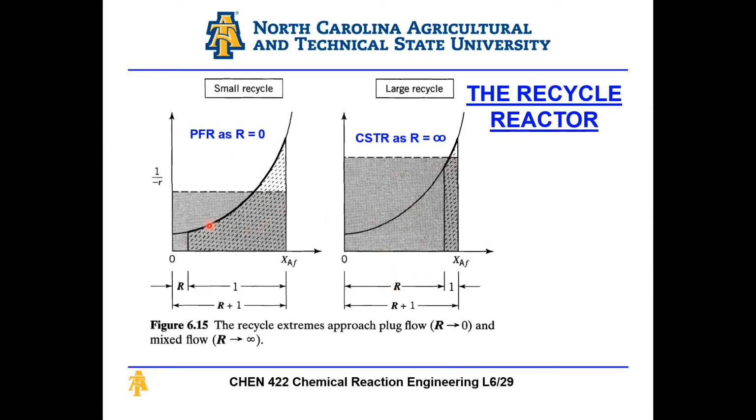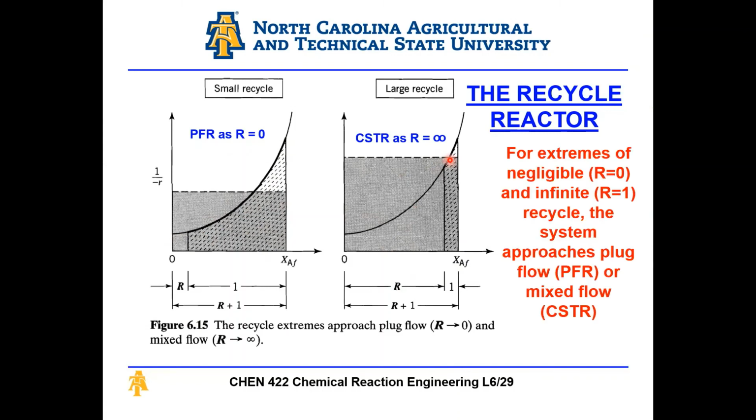So you need to be aware of this. As R equals 0, performance approaches a PFR. As R equals infinity, performance approaches a CSTR. So for the extremes of negligible and infinite recycle, the system approaches plug flow or mixed flow.